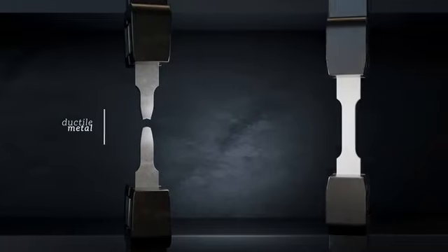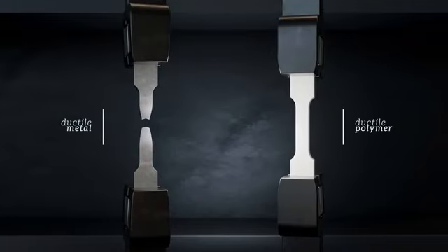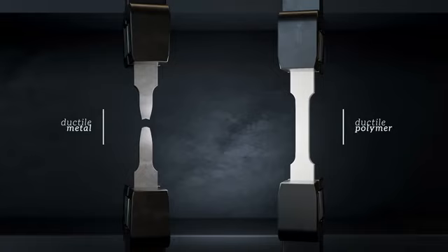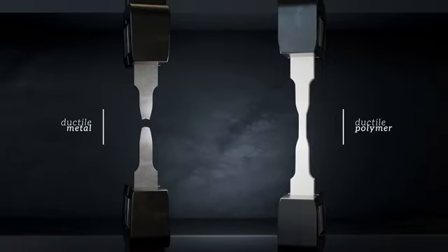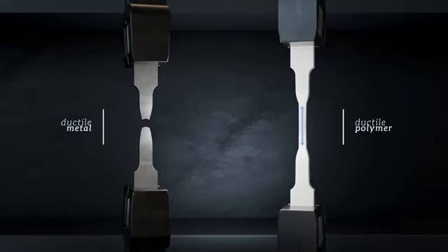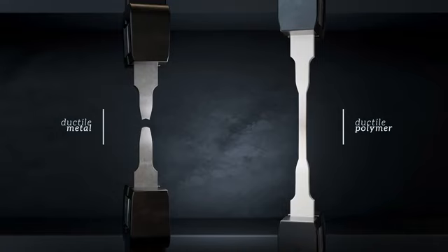Ductile polymers behave differently. A neck forms at the onset of yielding in a similar way, but the behavior after necking is different because the material undergoes a process called cold drawing, where the applied load causes the polymer chains to gradually align along the direction of applied stress. This realignment of the polymer chains strengthens the material and causes the neck to propagate along the full length of the specimen, instead of all deformation being fed into a single location. As the load continues to increase, the polymer will eventually fracture.